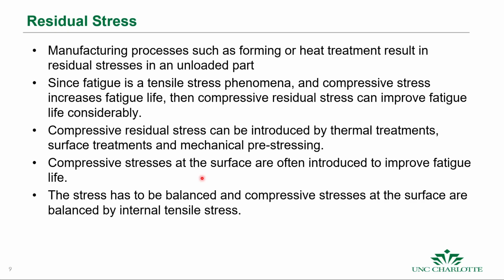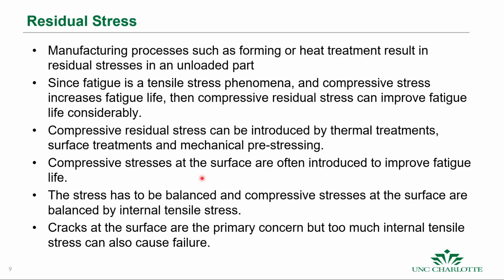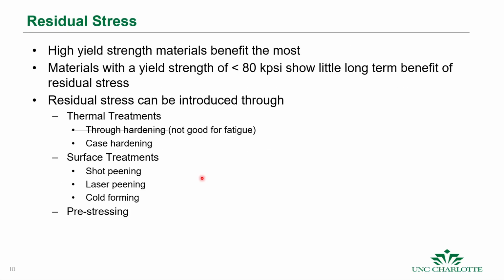And when we add these compressive stresses at the surface, we can knock down the stresses that are experienced due to loading. Okay. If there is too much internal tensile stress, though, it can also cause failure. So there's really an art to processing these materials in such a way that you can really stretch their life. That's pretty good. All right.